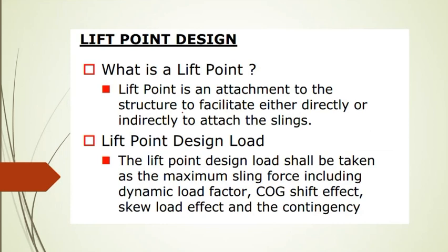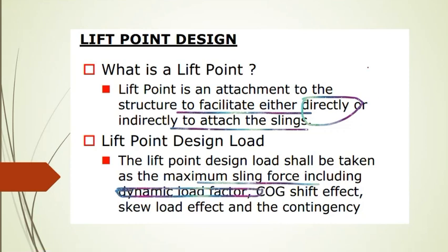Attachment to the structure to facilitate, either directly or indirectly, attaching the slings. Lift point design load: the lift point design load shall be taken as the maximum sling force, including dynamic load factor, that's a DAF, dynamic amplification factor, COG shift effect, and skew load effect, and then contingency factors.